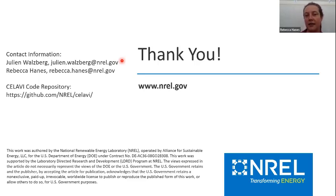So the reason in our case study why we found transportation costs weren't significant is because we included the option to do more extensive blade size reduction on site at the power plants. What that would look like is some kind of mobile grinding equipment would be shipped out to the power plant that's being decommissioned. All the blades would be shredded into very fine material. And then the shipping costs for that are at least an order of magnitude below the transportation costs for an entire blade or even a blade segment, which are both very, very difficult to transport. If you've ever seen one going down the highway, they're enormous. They're very hard to get anywhere.